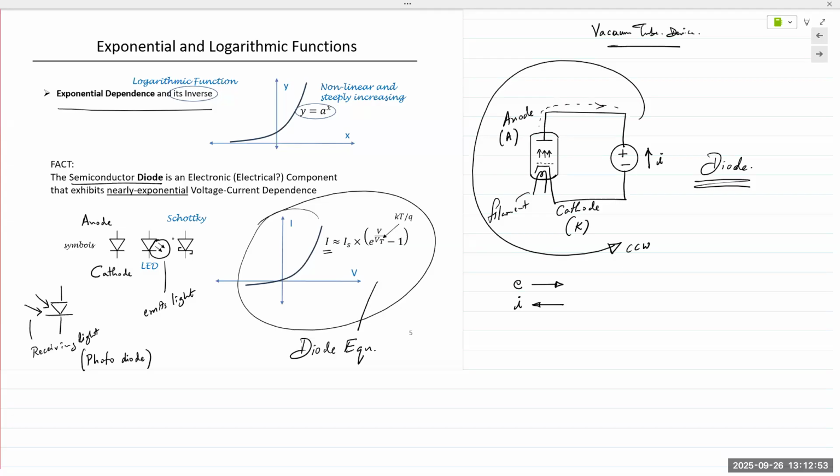Which is what all solar cells are. You have light energy falling on top of a solar cell. So you have photons coming in, impacting. Those photons impart energy to the semiconductor material. A small portion of that photon energy is transferred to the electrons. The electrons acquire sufficient energy to break their bonds and start flowing to the circuit. That's the basic operation of a solar cell.